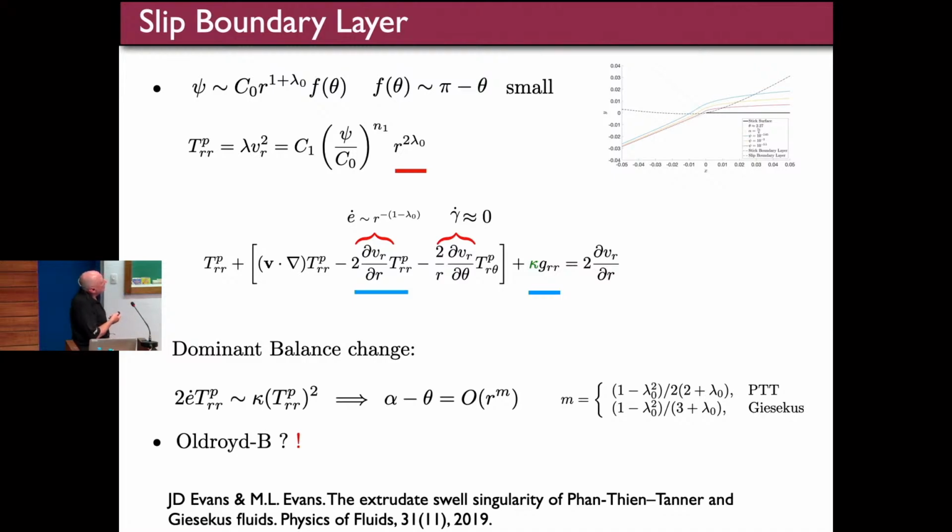That stress is arrested by the quadratic stress term. And if we do that, then we can determine the boundary layer thickness, and we can determine the behavior within the boundary layer at that slip region. And I'll show you a picture in a minute showing this transition of the stress between the three regions.